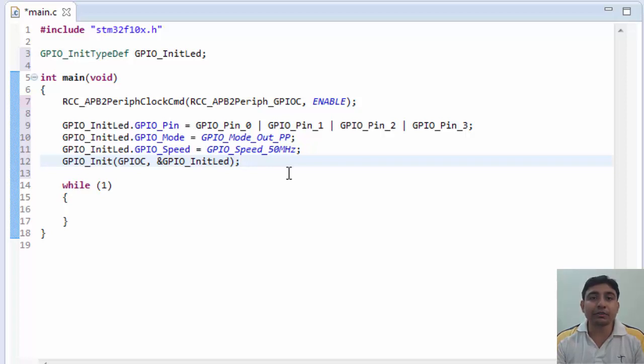So next is we need to decide which UART to use here as a receiver. Now if you remember, in the previous tutorial when we were writing code for STM32F4 Discovery board, we had a similar kind of situation where we decided which UART to use. So at that time I opened the technical data sheet for the microcontroller, and then we decided the UART 3 and PD8 and PD9 pins.